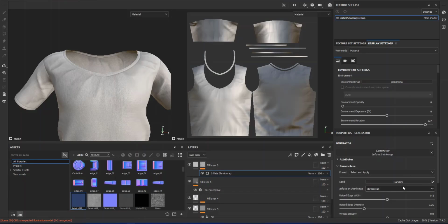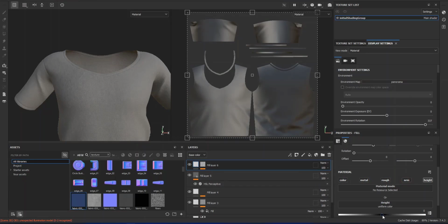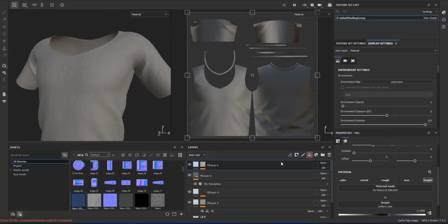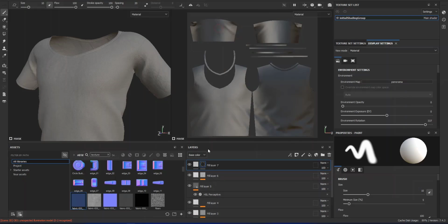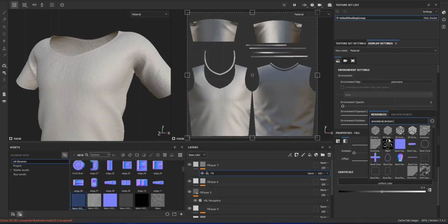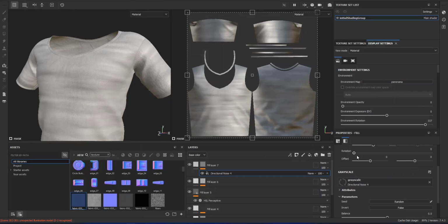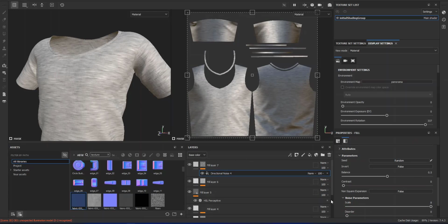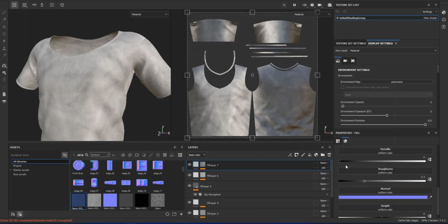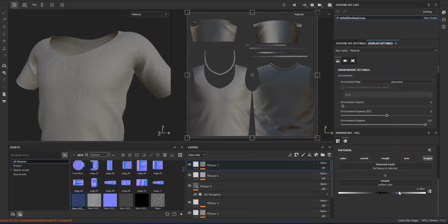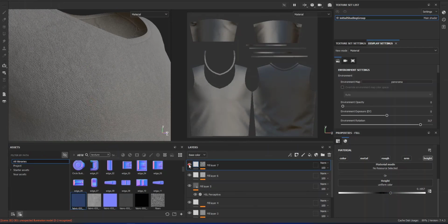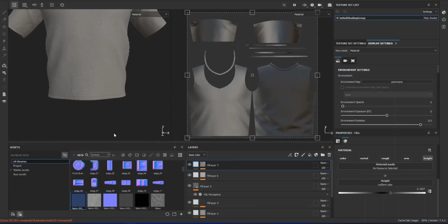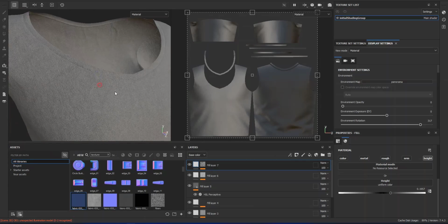We enter Maya and import the low poly model into the scene, and after placing the camera and adjusting the lights, we start importing textures. In the Hypershade, by creating an aiStandardSurface, we start connecting textures to each of our parts. Different nodes may be used, including Bump 2D, Displacement Shader, Divide. Then we assign the made material to the model. We start testing the renders, and in case of any problem in the light or material, we go to the relevant section and correct it to reach the desired light or material.